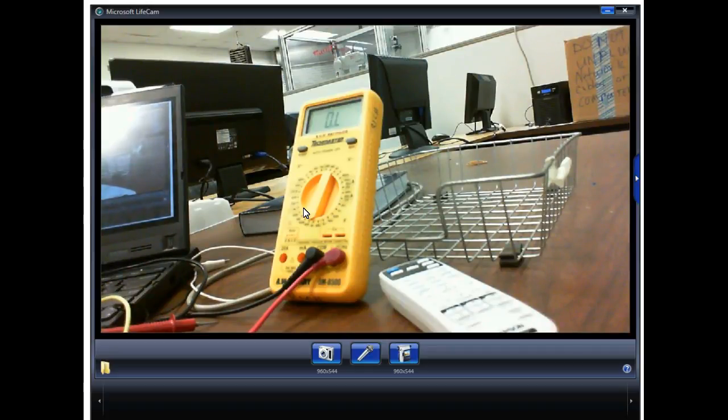We couldn't drive that with a common emitter. A common emitter has a moderate to high output impedance, right? The common collector has a low output impedance. We can drive speakers, solenoids, and motors with it, right? But we'd have to get our voltage gain out of the way before we got to the common collector. So we'd probably use a common emitter to get a real good voltage gain, with its high output impedance feeding the high input impedance of the common collector, which has a low output impedance, and we can get a real good current gain out of this.